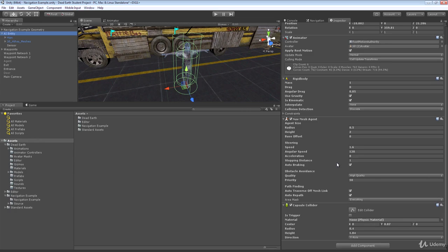For example, if we just did a simple distance check, we might be 1.1 meters away from our target. We might say if we're in a 1 meter radius of our target, then we should stop and move on to, say, the next waypoint. But at 1.1, we wouldn't be close enough to do that, so we would still think we have to move.